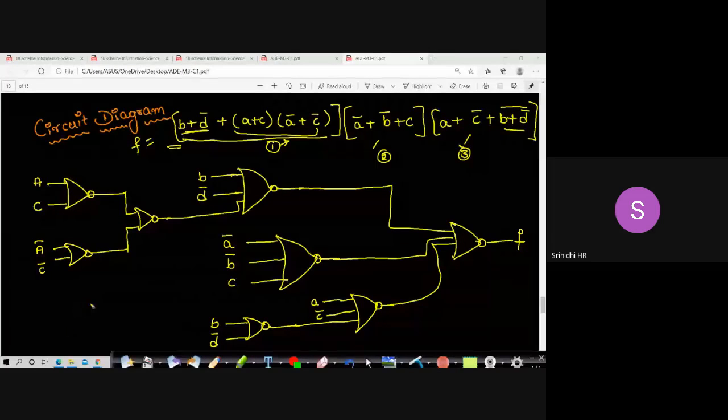What does the question state? In one single NOR gate, can it have any number of inputs? No, it cannot accommodate all these inputs at a time. So by applying the concept of gate fan-in, I have reduced this whole equation into sub circuits so that collectively you can generate your output here. Any doubts in this? Has everyone understood the concept? Can somebody unmute yourself and let me know whether you have understood? Yes, sir.